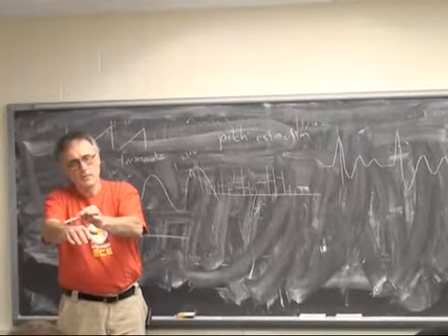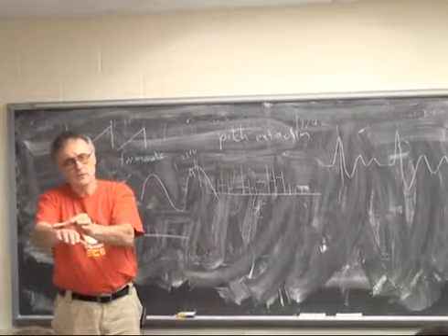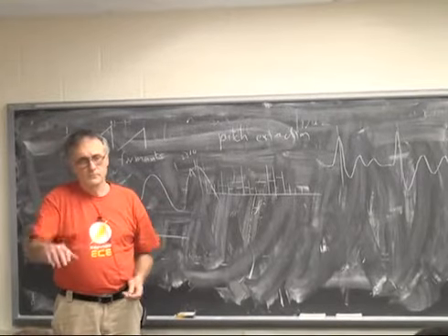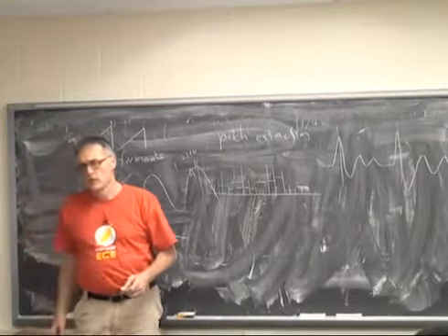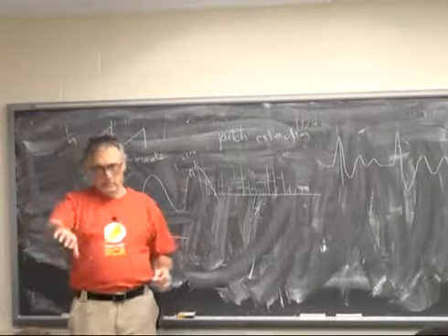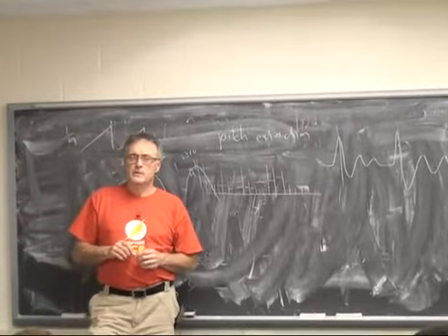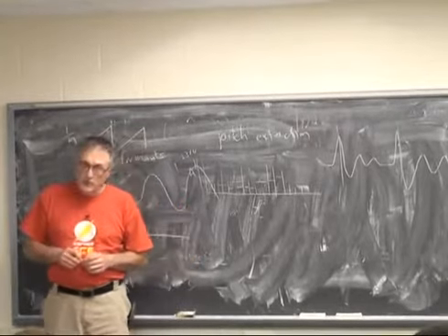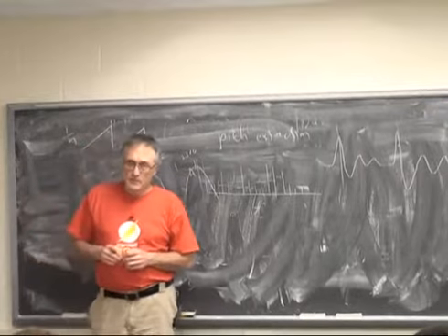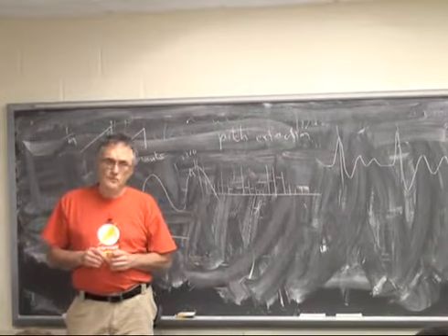So how do you compensate for the effects of gravity on the accelerometers? You need a gyro so you can get angle rotation. But getting position from acceleration is quite hard. It can be done, but requires temperature compensation and active control of errors.